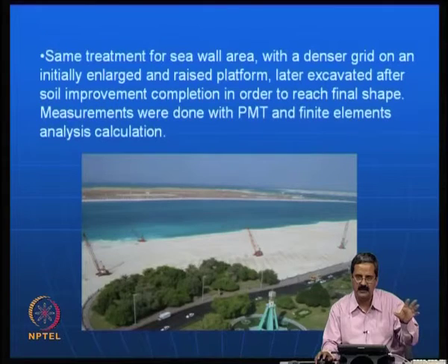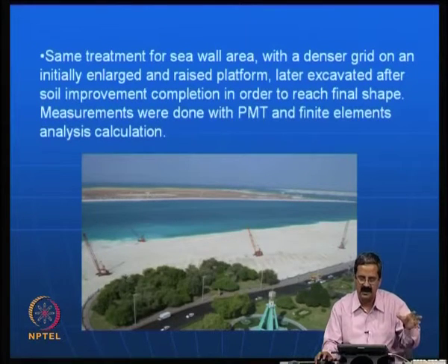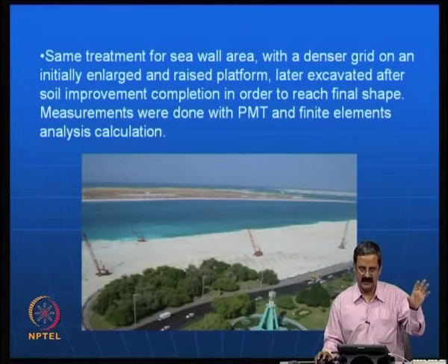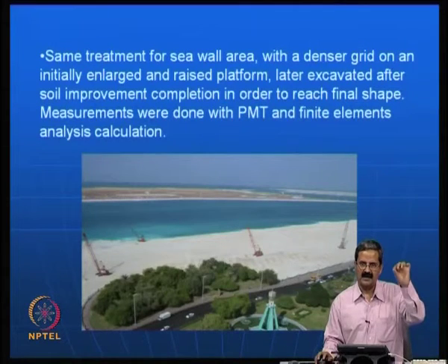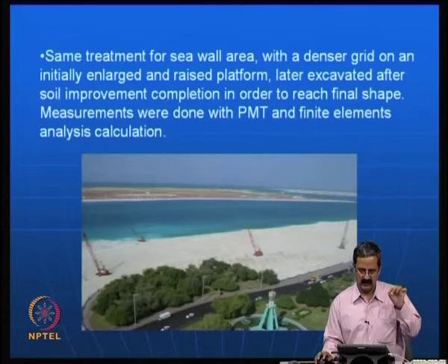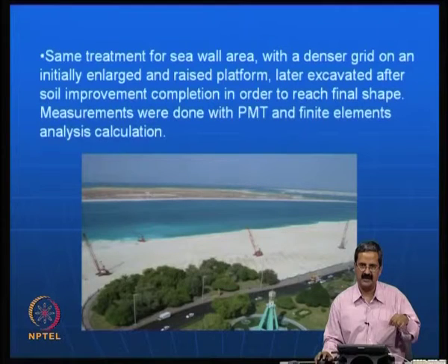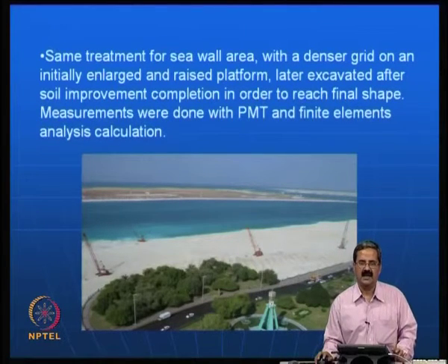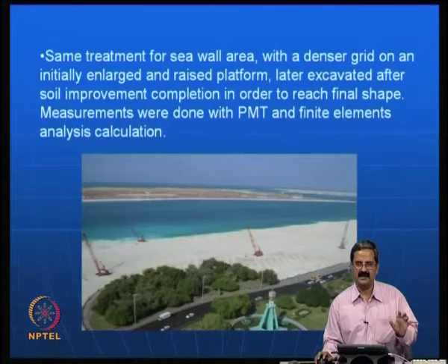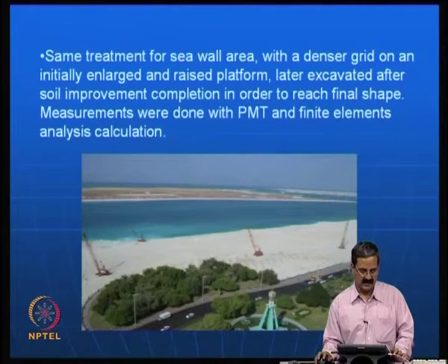Say for example, using even finite element calculations, you can simulate the whole structure at the top of the soil and then understand where the stresses are coming. Say for example, if the stresses are going to reach a very soft area, then the problem is that it could lead to a lot of settlements, and one should really optimize and see that those settlements are not there. And so these are some of the issues that one needs to understand and see that dynamic compaction is done in a proper way.